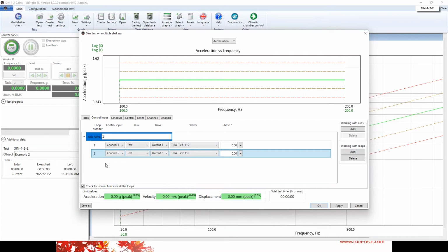The system will try to start up, but the calculations will be wrong, and in the end it will stop automatically because it will take a lot of time, and the system will stop this starting up process. So I recommend to double check control loops, all kind of channels connection, and you must be really careful with the sensor types.